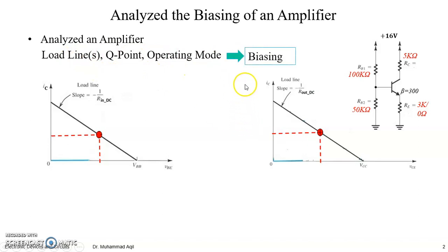So these are nothing but the biasing of a transistor for an application. For example, we have studied for amplifier. We already have analyzed a biasing scheme which is called the voltage divider bias, in which we have used two resistors by which we have set the voltage at the base with respect to the emitter to have a base to emitter junction forward biased.